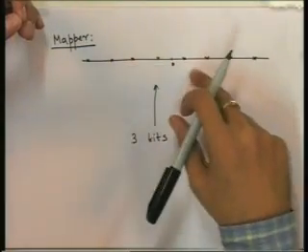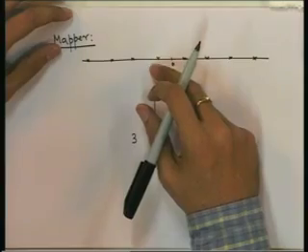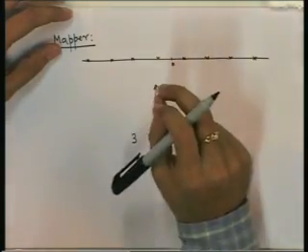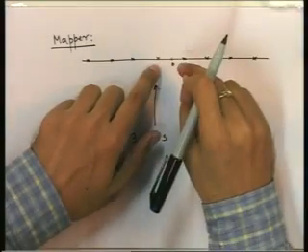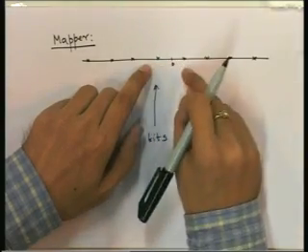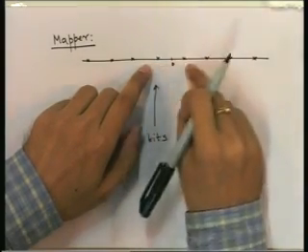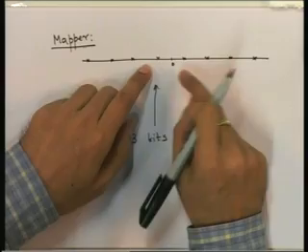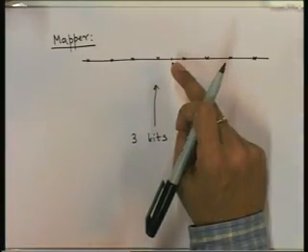What we should look for is that when at the receiver we make an error in detection, in estimating the point which was transmitted, there should not be too many errors in the bits. So, if we have some 3 bits here, some 3 bits here, and instead of receiving what we transmitted we received this, then the number of bits that are different between these two should be minimal. If there are more, then there will be more bit errors in a single symbol error.